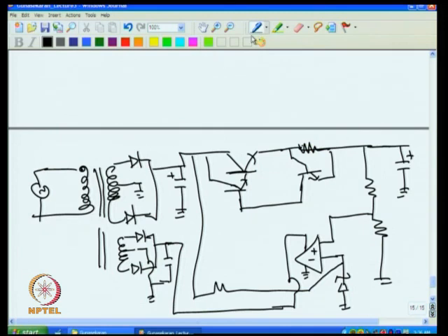Now what I do, I will connect this fellow, the output. Suppose I connect directly to the output like what we had done earlier, it will not work, because the supply voltage we have is only 20 volt, and this cannot go more than 20. So this output can go only up to 20, not more. If this itself is 20, then you have 20 here and 19.4 here, and 18.8 only is the maximum possible. But we want 100 volt, so we cannot connect this directly to get high voltage output here.